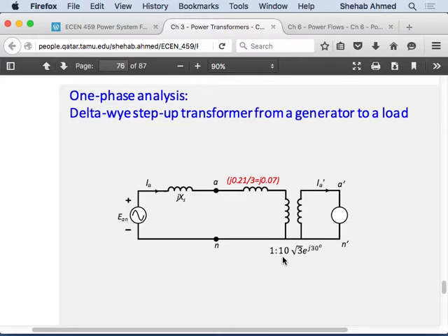I'm saying, what if they don't state it that way? If they state it as this is the terminal voltage of the delta star transformer, how do you solve it that way? This 10 times square root of 3 is correct, assuming that this was the turns ratio of the single-phase transformer. If it is the delta star transformer, it is not. It is 5.88 that we got multiplied by square root of 3. So both of them together would be the 10, not 10 times square root of 3. Does everybody get this? Right?